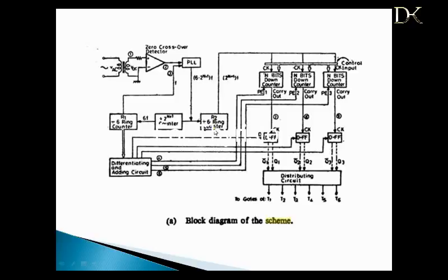The ring counter generates the necessary 3-phase synchronizing waveforms which are spaced at 60 degrees. The VCO output is divided by the 6 ring counter R2 to generate a frequency of 2 to the power of n plus 1 times f. This is used to clock 3 sets of n bit down counters 1, 2, 3.